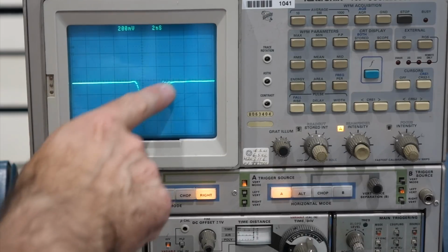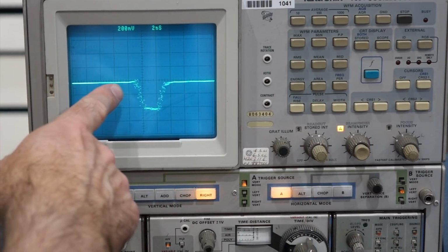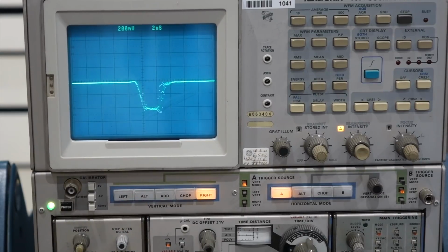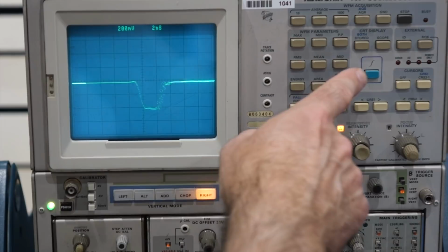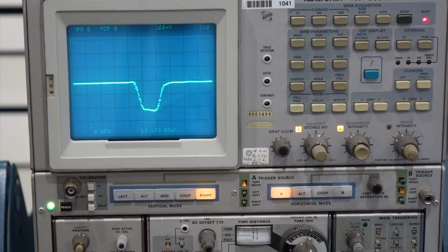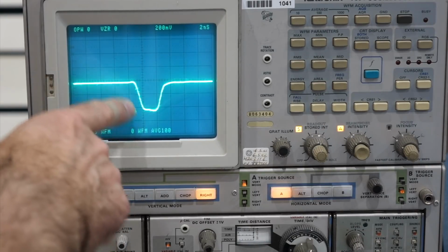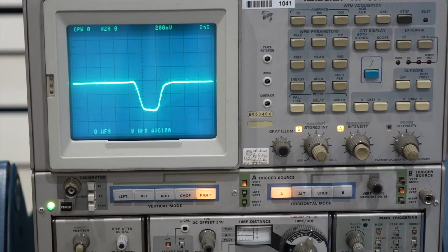And it has some artifacts to it, and that's because it's a repetitive measurement, it scans, so if there's some jitter, and it looks like there's repetitive jitter in the signal between the trigger and the pulse, it will do this kind of thing. But you just do an average measurement, get rid of that. And here you go, at 2 nanoseconds, it's exactly within spec, a 1 nanosecond rise time.